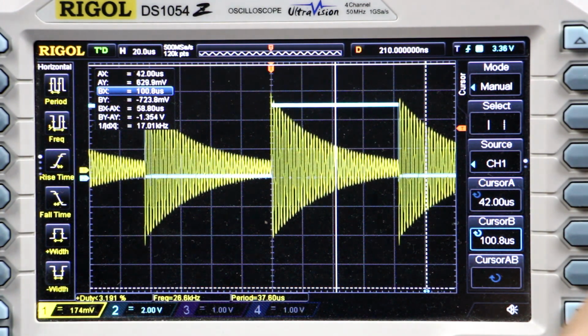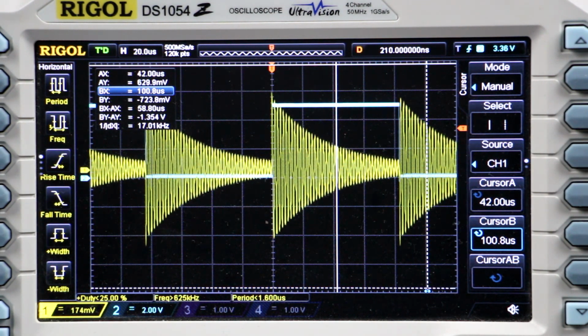but I won't repeat the measurement. Anyway, just by putting a capacitor in parallel to our coil, then we can determine the Q factor at any frequency we want. So that's the method of getting a whole set of values for the Q factor, because in some applications it becomes quite important really to know the Q factor at one specific frequency, and that's the way you do it.